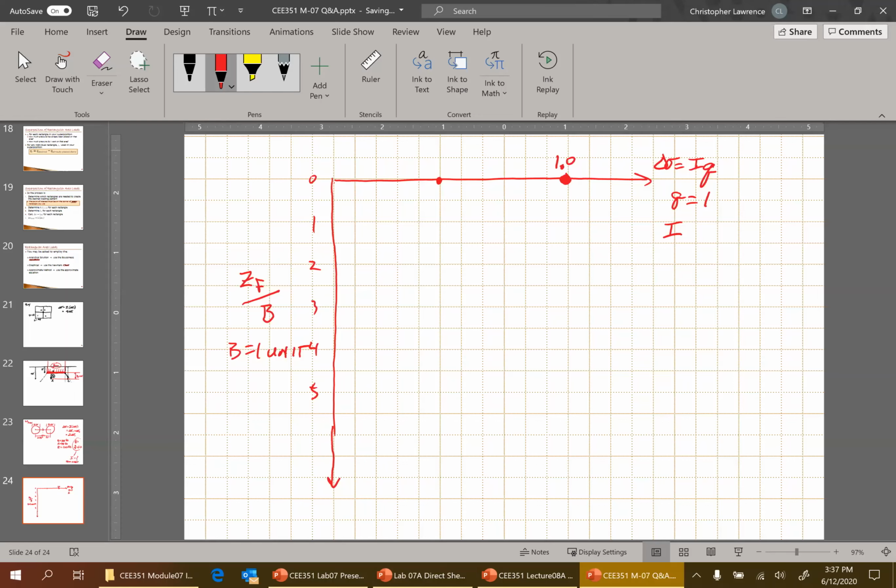So yeah, the square is going to come down like this. If you plot several values of I versus Z, it's going to come down like this. I don't know the exact shape, but something like that. Eventually it's going to asymptote. Eventually you get deep enough and there is no influence. If that's the square load, the square footing, what do you think the strip would look like relative to that?